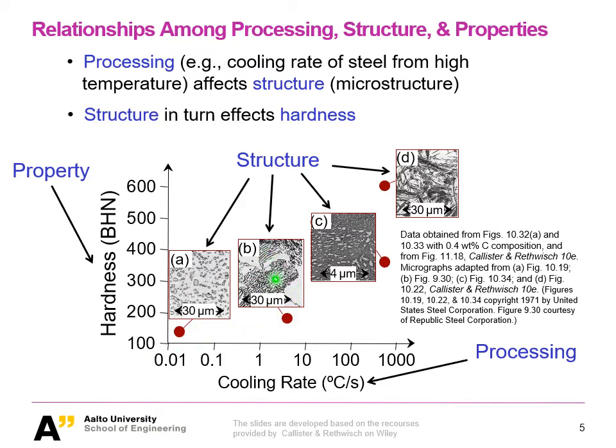And then you will get this nice large grain pearlite structure, yeah, plus your ferrite. So that gives you a phase that, compared to spheroidite, is harder, but relatively still soft. Yeah. And if you just further increase your cooling rate, what do you get? Yeah, you get martensite, right? So this is the very fast cooling rate you can see here.